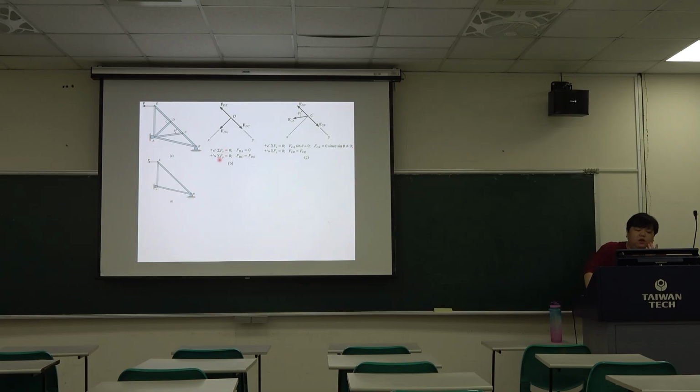And then when we do the summation Fy equals 0, with the axis also, just these two, this is equal to this. So DA is a zero force member.